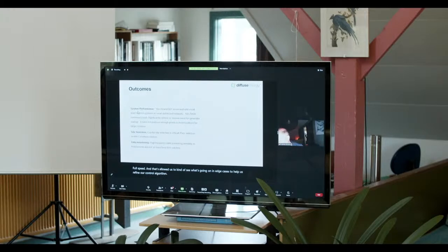So the outcomes of this last couple of years of testing is we've seen that originally we were aiming this at the larger point-to-point antenna arrays, which sit around 700 watts to 1.5 kilowatt continual load. Unless it's a really, really good site, a single turbine is a bit undersized to have a good impact.